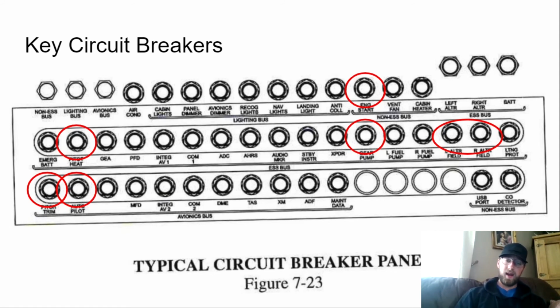Well, on the circuit breakers, and I wish it showed it in this schematic, but they don't, there will be a number, and that number tells us how many amps that specific device is pulling. So it makes sense to start with the unnecessary and high amp circuits first. To do that, simply pull out that circuit breaker and you've shorted out that circuit, no longer drawing energy from the battery. So, really effective and timely load shedding can save you precious minutes of battery power and allow you to safely end a flight.